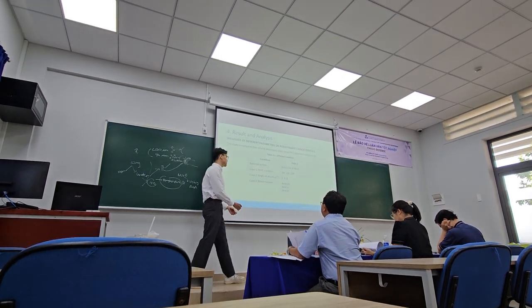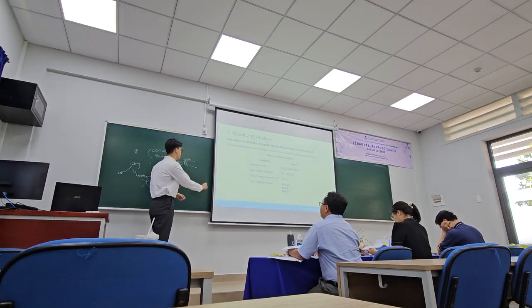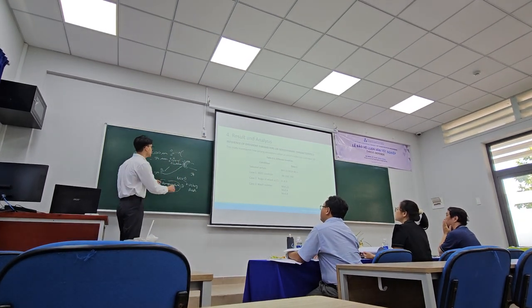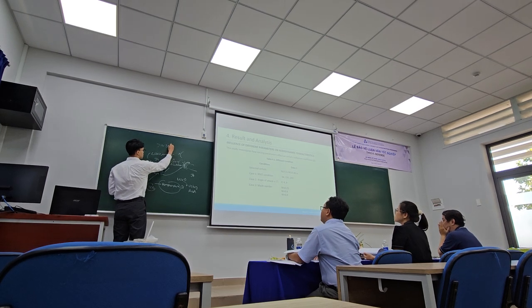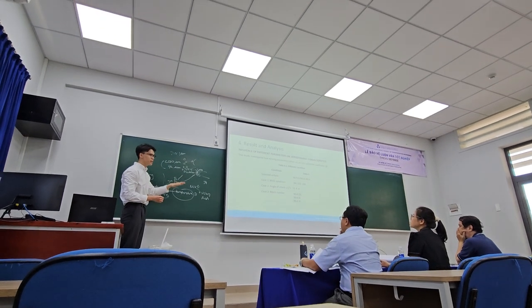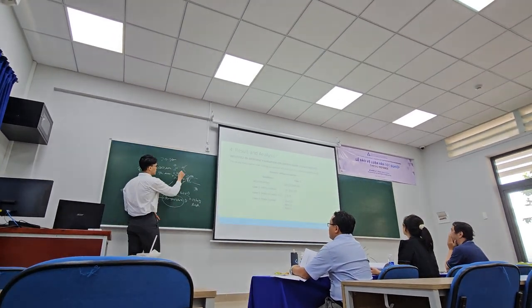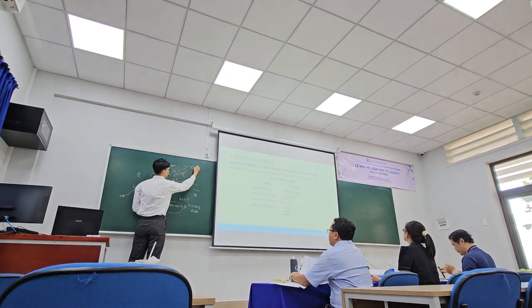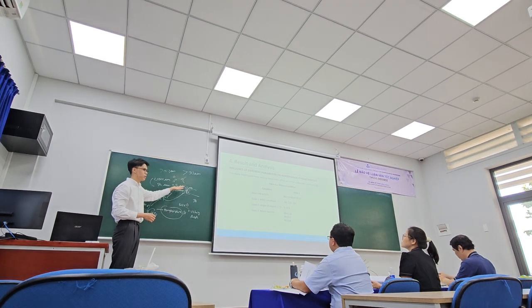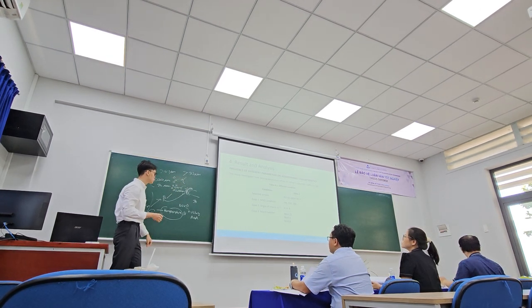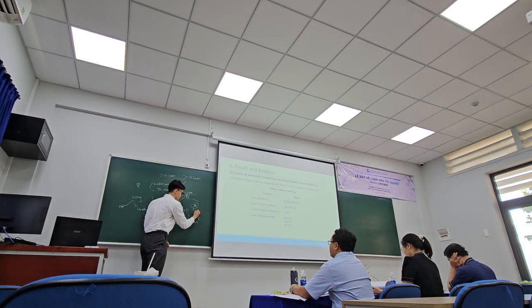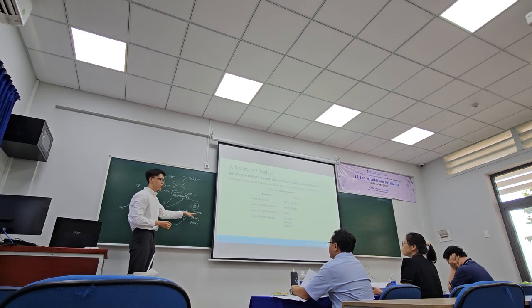First of all, I will come to case one. The reason why I start from 94 is that in the definition, the supercooled droplet just needs to be greater than 50 micrometers, but in fact, with this diameter they still consider the droplet a small one. In reality, droplets greater than 90 micrometers are considered supercooled large droplets, with their own equations and phenomena. So I start from 94 because this is from the NASA experiment. I take the first case from NASA to validate my results.